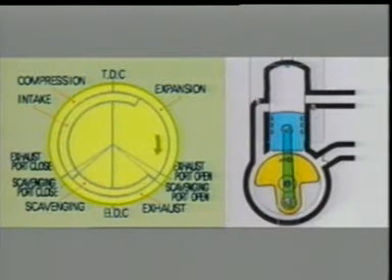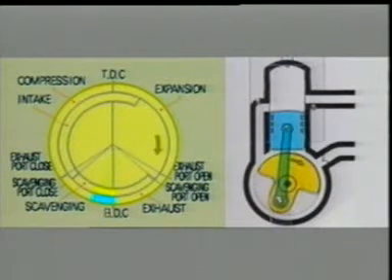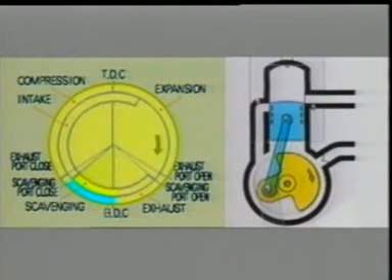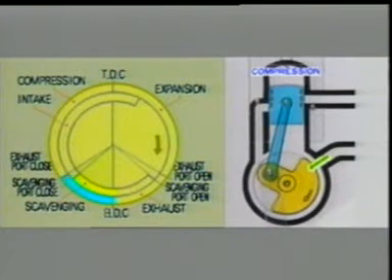As the piston moves on the upstroke, that is, as soon as the scavenging port in the upper cylinder chamber is closed by the head of the piston, a vacuum is created in the crankcase chamber and this causes mixture to be taken in. As the piston head rises further, it closes the exhaust port further up the wall of the cylinder and begins to compress the mixture in the cylinder.